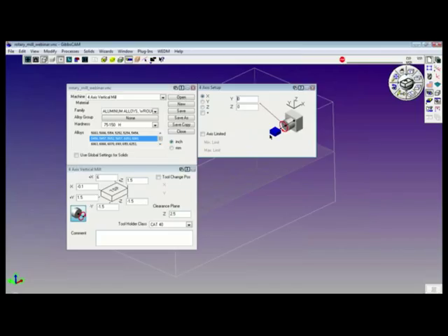They come in and they touch the standard with all their tools to set the values there. Other times you can actually touch the top of the fourth axis, or if you've got a tool setter, you can establish the distance that way. So it's important to understand that the tool Z offset is the center of rotation on your part.